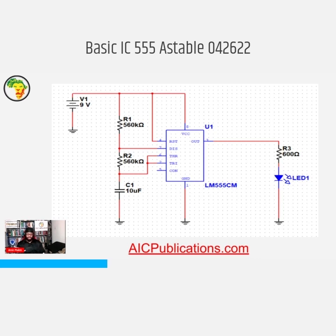This configuration with these two resistors and the capacitor is what creates the time constant that controls how long the light will pulse. On the output side, which is pin 3, you see R3 and the light emitting diode. The reason we have R3 is that anytime you use a light emitting diode, you always want something that controls the current so the diode doesn't get too much current and burn out. So that's the purpose of all of these.